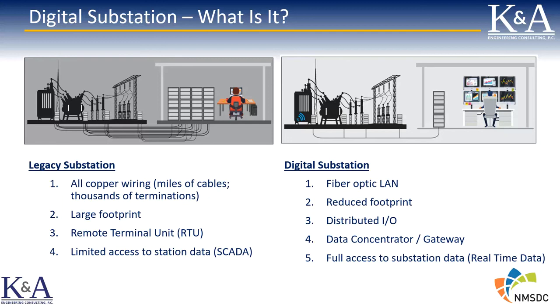That's what you see in the left-hand picture at the top, where all the copper cables are coming into the control room or the relay room at the substation and have to be terminated. All those signals eventually come to a remote terminal unit. There's limited information available in this type of legacy substation. You basically have access to SCADA information and not much more than that.